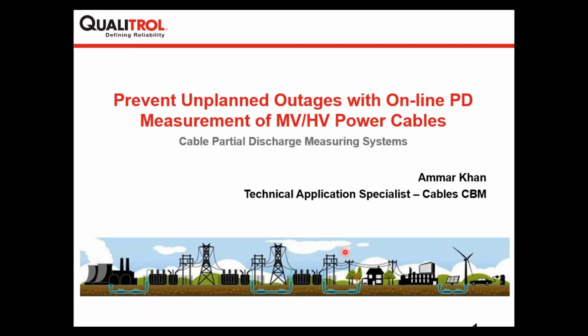Yeah, actually, you are all talking about the neural network technology or the support vector machine or the fuzzy logic technologies to classify between partial discharges or the noise. But from Qualitrol's perspective, we have been using artificial neural networks for our other expert analysis systems, but for the cables, as you can see, we are only discriminating between the noise and the PD, partial discharge activities. So far we are confident with the same technology and we are getting very confident results.